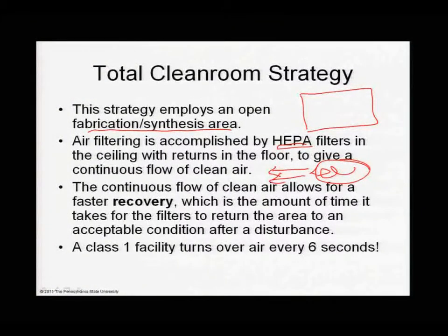and you can keep the room as clean as you want, depending on what clean room level you're striving for. So the flow is in, through the room, out through the floor. The air is filtered, and then back in again. Remember, in the glove box, which was a small glove box, it was an inert atmosphere doing this. This is air now. This is a large volume. This is the ceiling. This is the floor. The air is constantly purified.